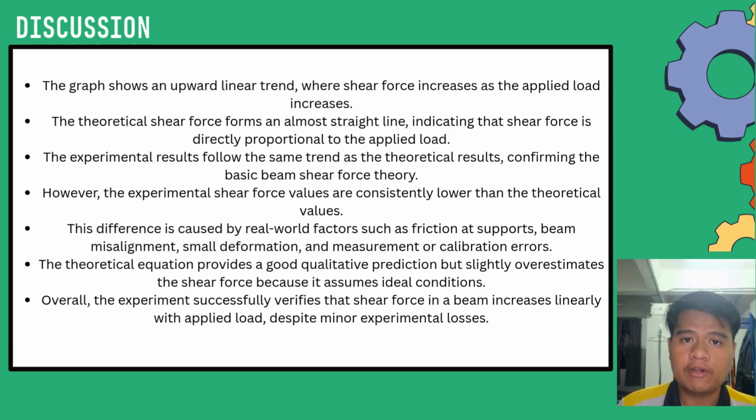Overall, the theoretical equation provides a good prediction of the trend, but slightly overestimates the shear force values. Despite this difference, our experiment successfully verifies that the shear force in the beam increases linearly with the applied load.